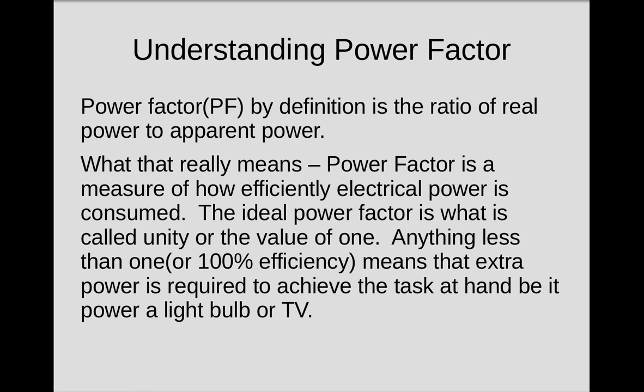So knowing that, you want to make sure you're using very efficient lighting, very efficient TVs, very efficient electrical devices, but understanding how power factor works will help you understand really how efficient that device is. There's a difference in using less real power and using less wattage. That's what we'll try to explain here. So the ideal power factor is what is more commonly referred to as unity, or the value of 1. And 1 is considered to be 100% efficient, meaning it takes the same amount of volt amps and watts to power the device, which means it uses the exact same amount of power to arrive at the wattage that it's rated for. I'll explain a little bit more about that in a demonstration.